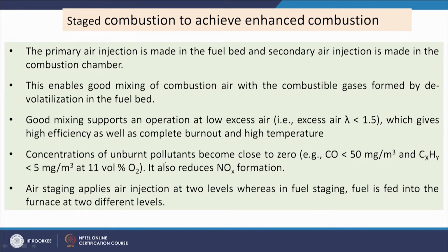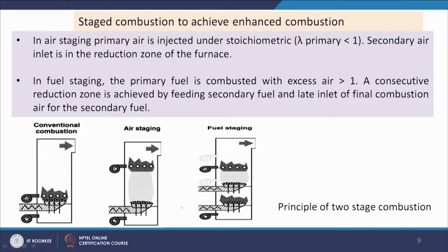Concentrations of unburnt pollutants become close to 0 in this case, and air staging applies air injection at 2 levels, whereas in fuel staging fuel is fed into the furnace at 2 different levels. Okay, so, here we see that it is conventional combustion and here air staging. So, air is provided here primary and this is secondary air, and fuel staging. So, here we are providing primary air and then secondary air, and again we are providing the feed also. So, that way different steps or stages can be implemented